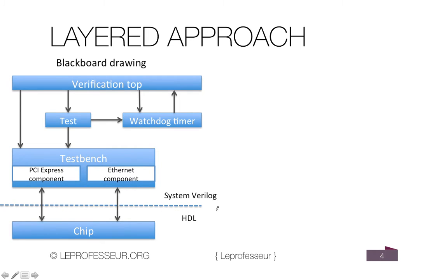and then we can draw a line here which separates our HDL, hardware description language, versus our SystemVerilog verification environment. Okay, so HDLs are good when you wanna design the chip, but those are not very good when you want to verify. For verification, we need extra features as I was just discussing a minute ago, right? So this is a typical, very basic theoretical model for a verification environment. When you discuss among your team members, you're gonna decide what we need, which module, who's gonna develop it. Okay.